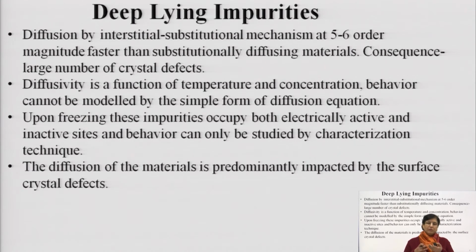So, whenever we are carrying out diffusion in an oxidizing ambience or some other enhanced diffusion, you have to ensure that there are minimum crystal defects. Similarly, another thing is that diffusivity is also a function of temperature and concentration, and you cannot model such behavior with the mathematical models which are available.